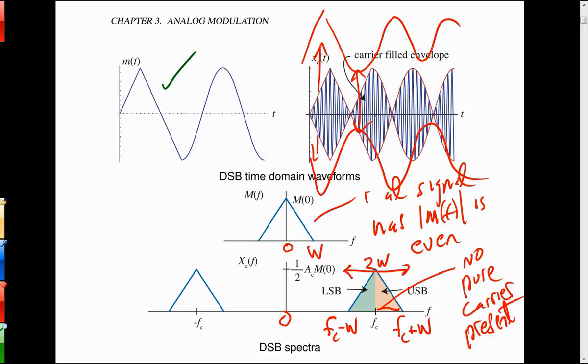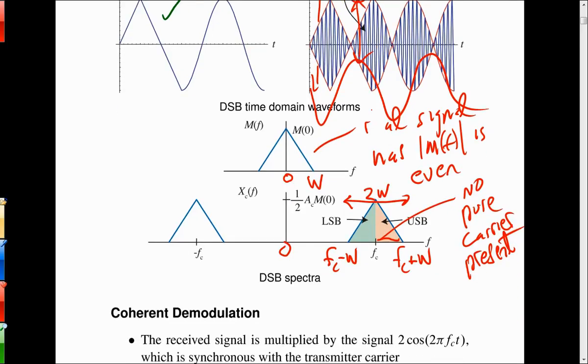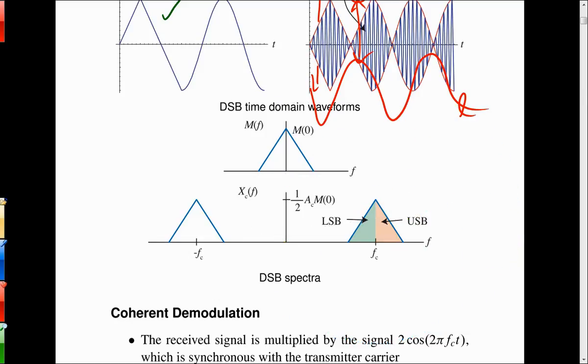In the frequency domain, it's not really that much different, and I think that's probably what you were being perplexed about, Rob. Let me get rid of some of that clutter. In the frequency domain, this is the double sideband spectrum. If I add in pure carrier, all I'm doing is adding a pure spike sitting there at the carrier frequency. A much different view of things than what the time domain does. But that's what the pure carrier is doing.